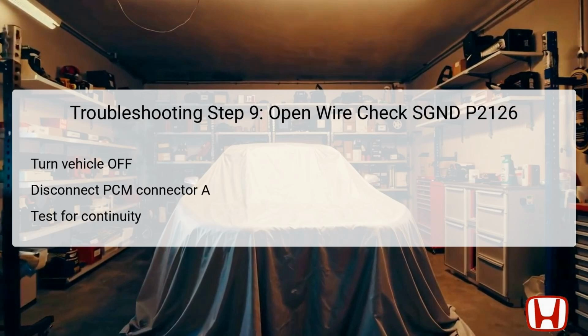In wrapping up the troubleshooting process for DTC P2126, you will now check for any open wires in the SGND signal ground line. Begin by turning the vehicle to off and jumping the SCS line for stabilization. Disconnect the PCM connector A51P, as earlier steps have shown. Use a jumper wire to connect the APP sensor's number 2 terminal to the body ground for continuity testing. This allows for a final assurance check of the SGND wire's condition.